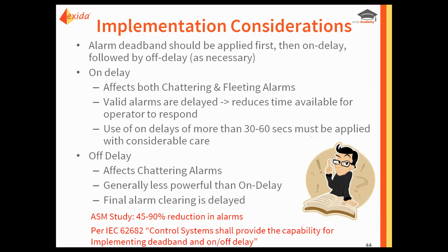Another thing that's quite interesting is if you look at the IEC version of the alarm management standard, that's the international version. There are actually requirements in there related to control systems providing the ability to implement deadband and on-off delay. So that means going forward, if you're a control system supplier, this is a requirement to have in your alarm system.